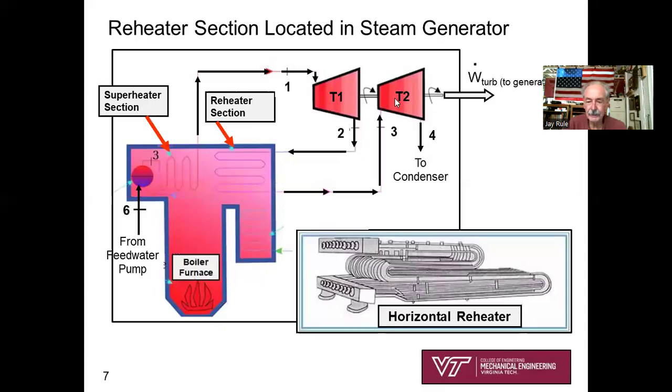Okay, and what would this look like in the world? Well, here's a picture of our boiler furnace. I've shown my steam drum, where I've got saturated vapor coming out. And then you've got a superheater section going into state 1, very similar to the textbook sketch. Coming back from turbine 1 into a reheater, out of the reheater up to T3, into turbine 2, the lower pressure turbine, and then state 4, the condenser.